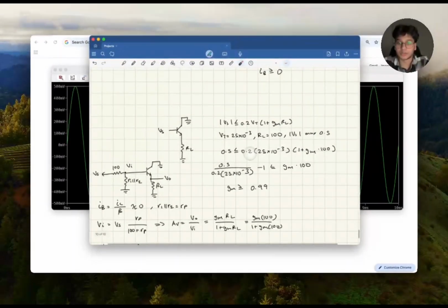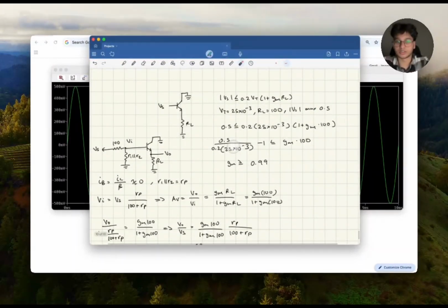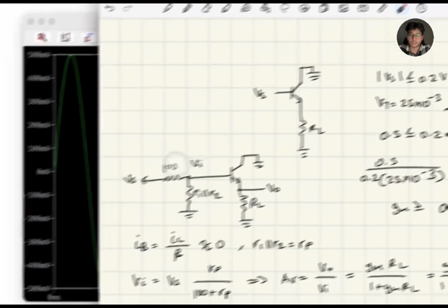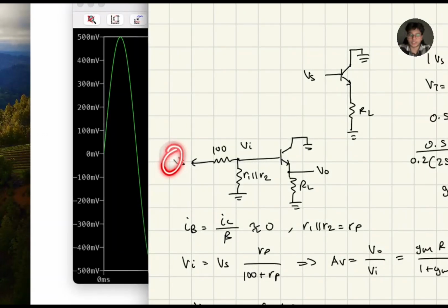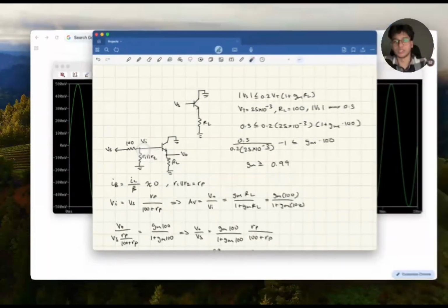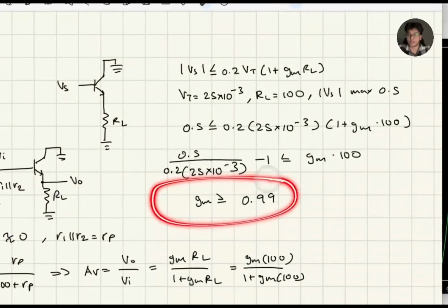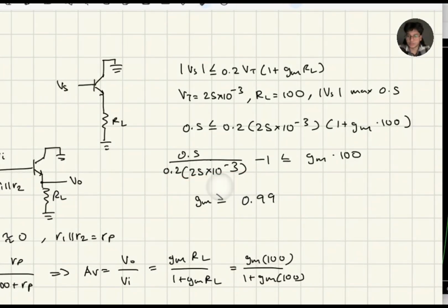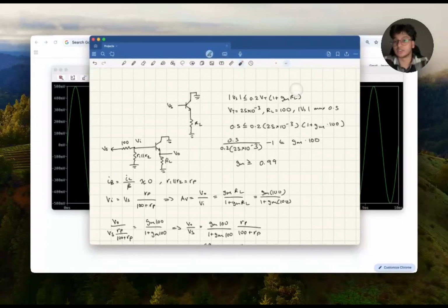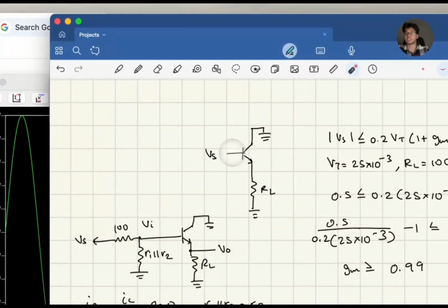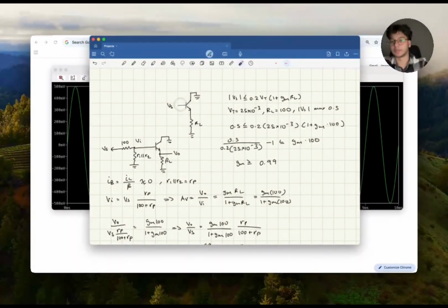Now, here is the small signal analysis that I did to get the resistance values. This is a dumbed down version of the circuit, which I used because I assumed that the voltage coming in is going to be relatively close to the voltage going out. Now, this isn't necessarily true, but I did this because I wanted to do the transconductance calculation. For the transconductance, you just simply need a range of the input voltage, which is in this case the voltage at the base.